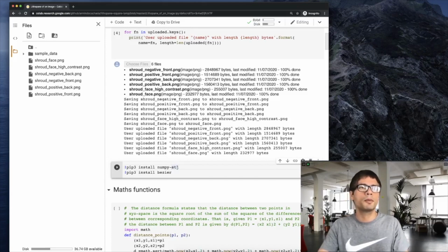So typically applications like Blender will be able to open this file, and you can change them, or you can use the STL files and, for example, import them to Cura, which is a software used by people into 3D printing, and convert the STL into G code, and the G code will then be used to print the object.